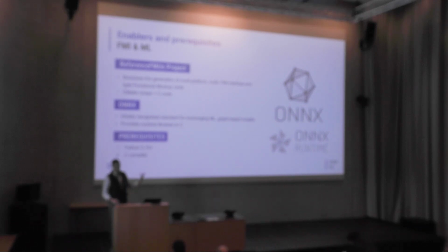Then, if on the one side we have the requirement to be compatible with FMI, on the other side we want ONNX models to enter functional mockup units. ONNX is a standard for machine learning models, and it makes available a runtime library that we need, of course, to run inference from the models in C. So we were able to find a very easy software and language setup based on C. The only prerequisites are to have Python 3.10 and a C compiler.